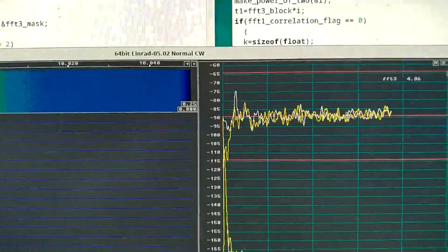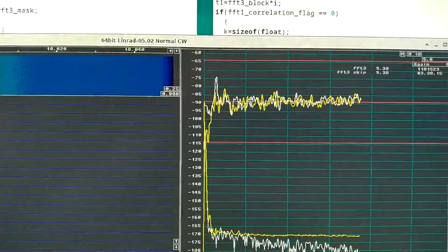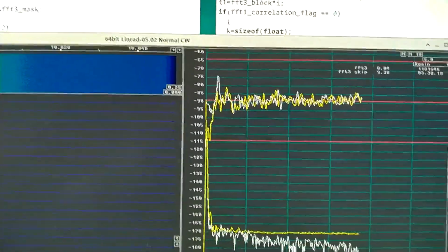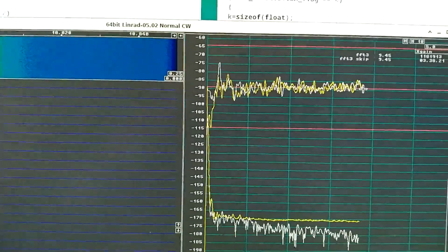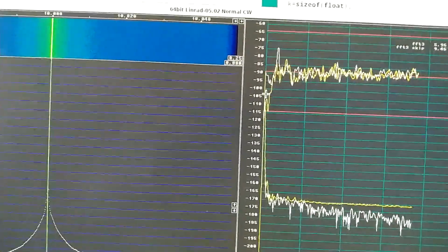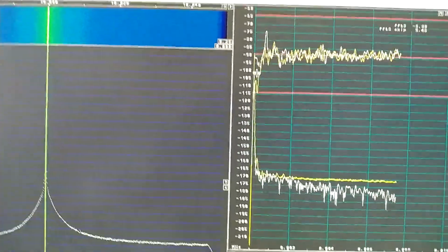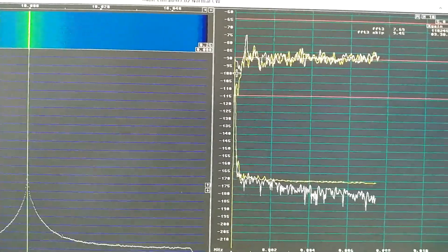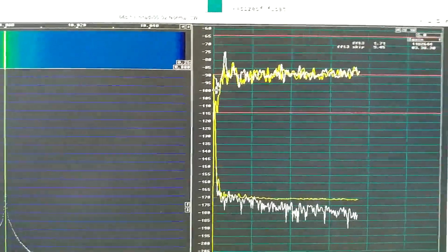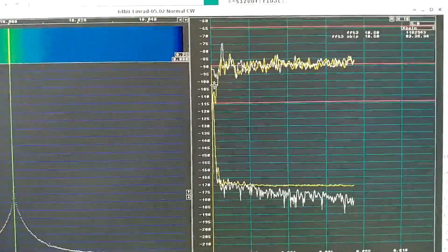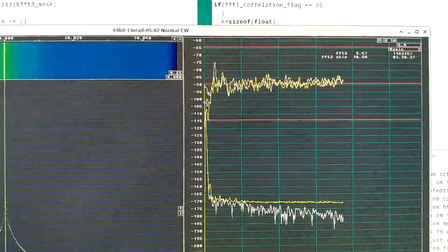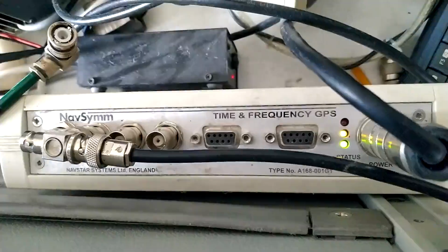But I can see here that the amplitude and the phase noise, they are not correlated at large frequency offsets. What happens here in the close range, I'm not so sure I can trust after having set the parameters I'm using now. This can be better studied with the sound card than with the SDR eyepiece.